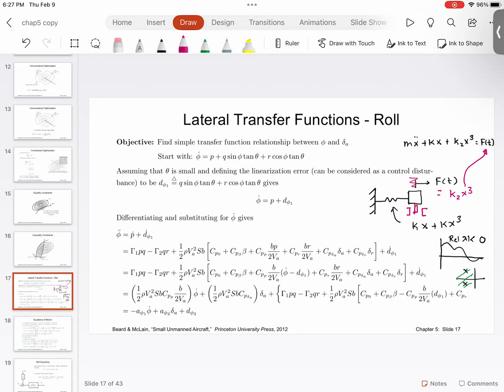Everyone understood this? Now, some of you may ask me, now what? Understand that the resulting equation after the nonlinear feedback is linear. Then you can use any linear technique to control it, such as the transfer function. That is the key. And in certain cases, if you have some residual effect that you cannot cancel out, you would give it some additional controller input. So you will make the electromagnet stronger than what it should be, to compensate for the effect of disturbance. Everyone understood this?